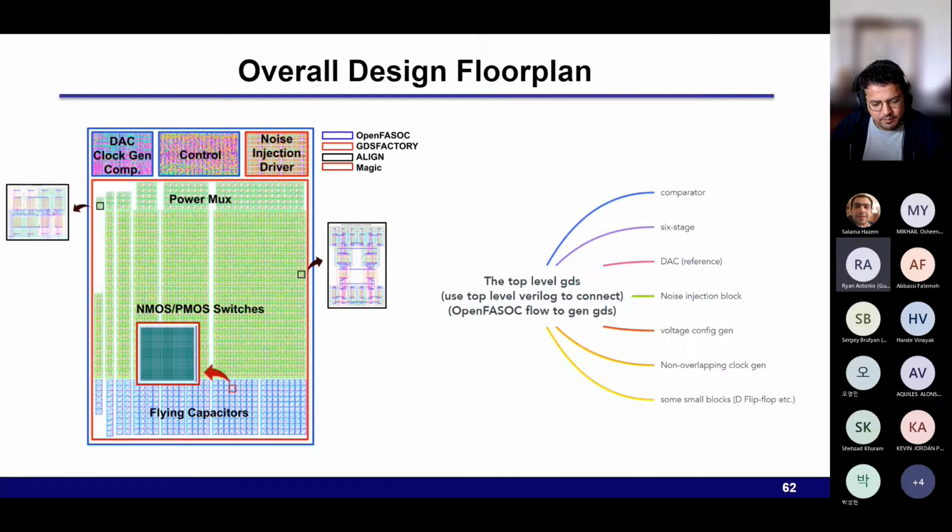Yeah, I mean, the solution is basically that you do not write LVS or DRC decks in a specific dialect, but you generate them from tables or something like that. So some generic way, and then you can generate it for different targets. Yeah. I mean, unfortunately, I think that Mentor pays the foundries a lot to only supply SVRF rule decks.